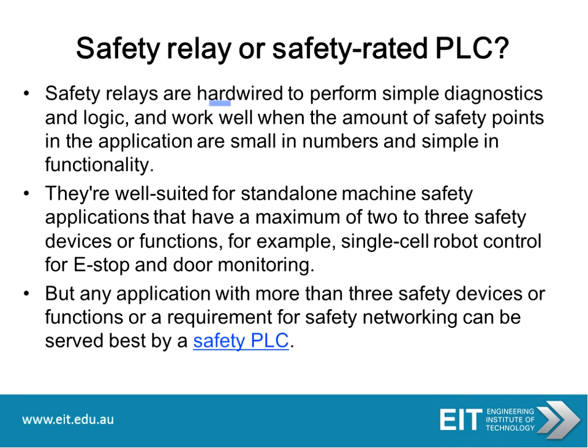Safety relays are hardwired to perform simple diagnostics and logic, and they work well when the amount of safety points in your application is small in number and also simple in functionality. So they're well suited for standalone machine safety applications that have a maximum of 2 to 3 safety devices or functions. For example, a single cell robot control for e-stop and door monitoring. But any application with more than 3, so that's the guideline again, more than 3 safety devices or functions, or a requirement for safety networking, can best be served by moving over then to a safety PLC.